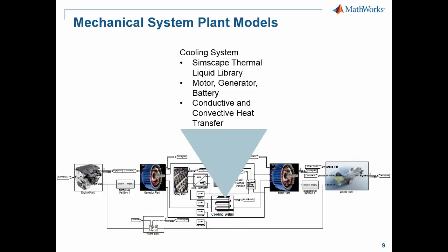We also model the cooling system using the SimScape Thermal Liquid library. The motor, generator, and battery have liquid cooling circuits attached to them, and we can model the conductive and convective heat transfer from each component. I will now switch back to the model so you can see the mechanical plant models in more detail.